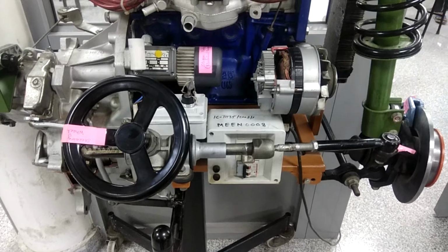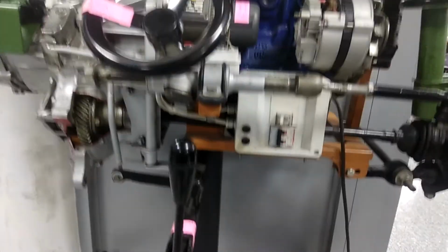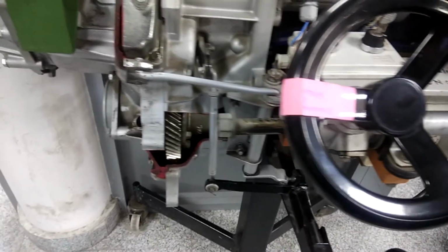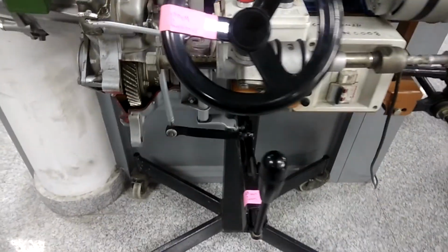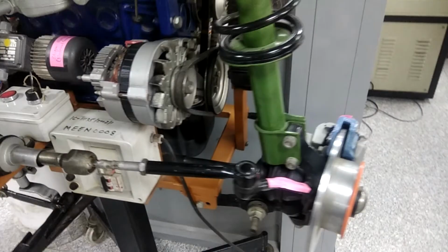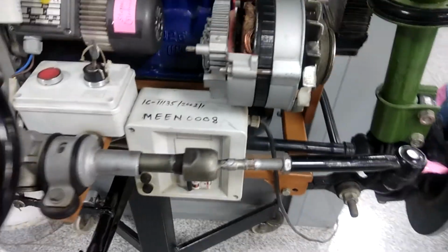So now let us focus on the working of the steering mechanism. The steering wheel rotates the steering column. Steering gearbox is fitted at one end of the steering column. Due to rotation of the steering wheel, cross shaft in the gearbox oscillates. Cross shaft is also connected to the drop arm. Drop arm is linked by means of a drag link to steering arm. Steering arm is connected to front steering wheels with the help of tie rods.